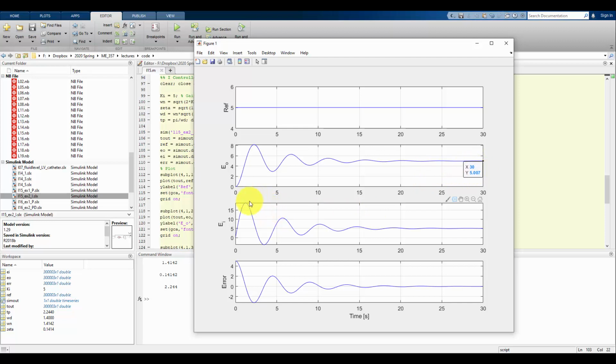However, with a gain of 2, a drawback of that was that our peak voltage is now about almost 19 volts in order to achieve this. But we got a smaller peak time, and we also see here that we have our overshoot here, it goes up to about 8 volts. And finally, for